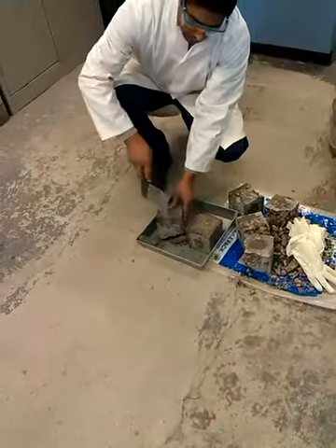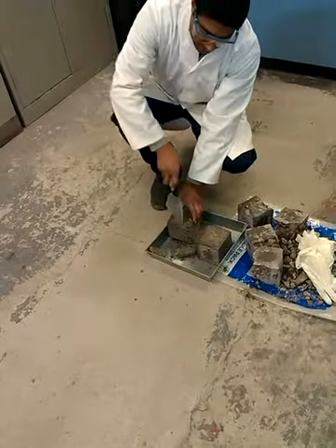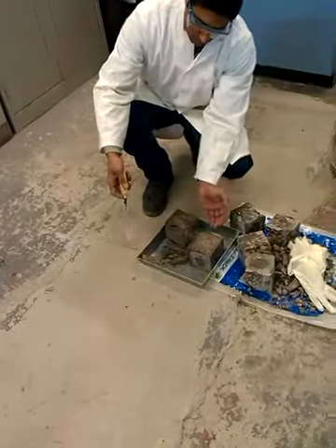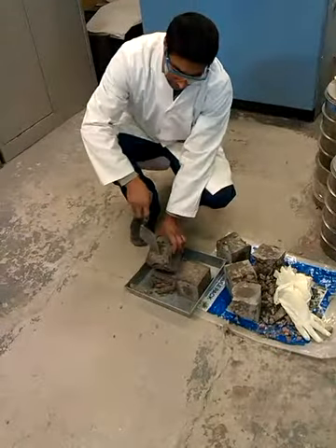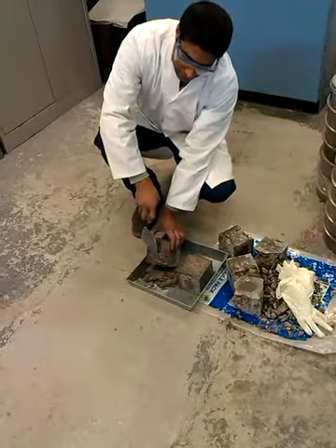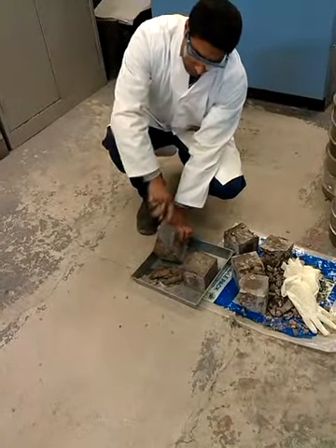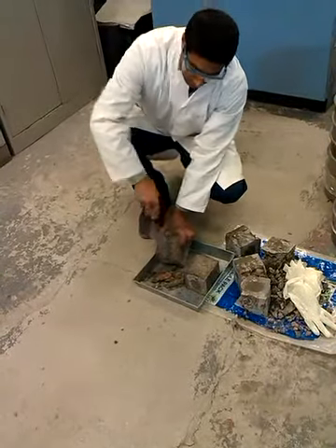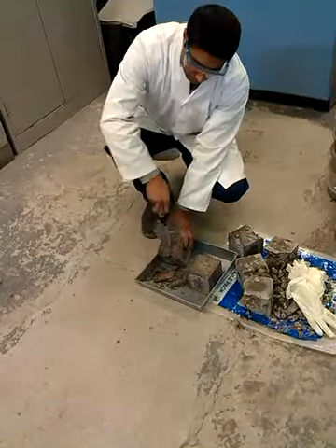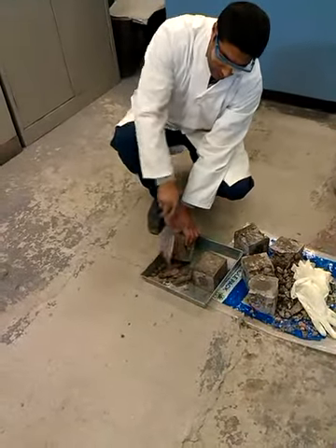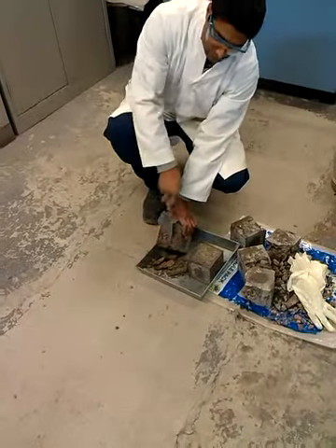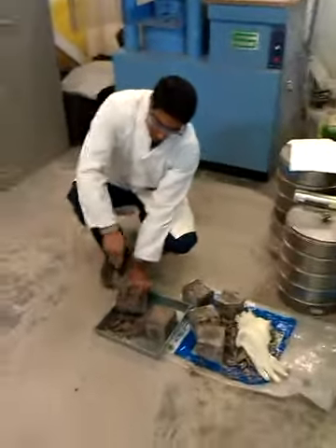Now the other thing is checking how it has failed. There are many ways, but normally two ways: shear failure and bonding failure. If the concrete fails with the shear failure, that will be the stronger type of concrete. If it fails with the bonding failure, that will be the weaker one, right? Because in the bonding failure, the bonding between the materials will be very weak. There will be no bonding between the materials. That's why it will be a much weaker type.